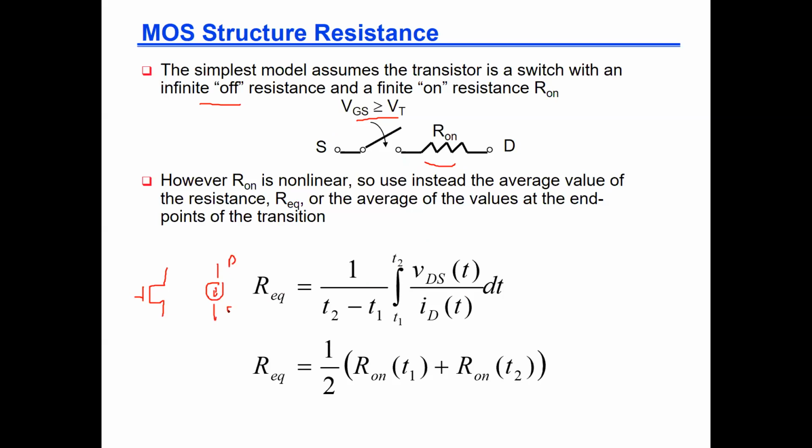Okay, and this current value is changing, and therefore as VDS changes, we can model it really as a variable resistor between the drain and the source. But we cannot always afford to model it as a variable resistor, because that's what simulators are for, they take every time point. We need to model it by some equivalent or effective resistance.